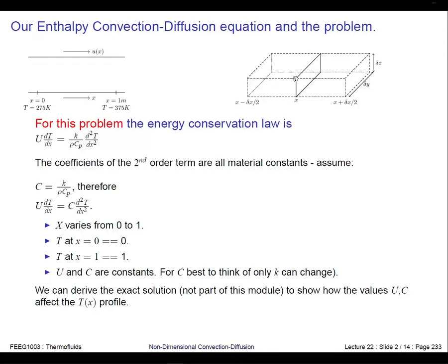And we did this applying a control volume, and we said, well, we know what's going on in the middle of the control volume, and we did the Taylor series to extrapolate the information to the faces, and then we said, well, we need to work out what the convective and the diffusive fluxes are on these faces, and then we said it's a steady flow, and there's no energy creation inside the control volume.